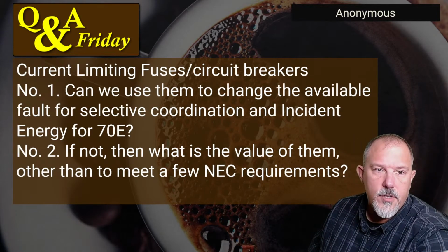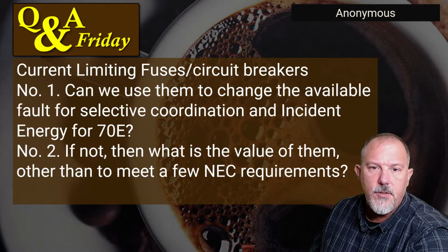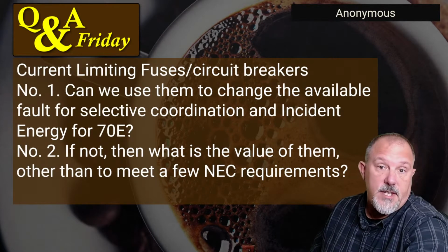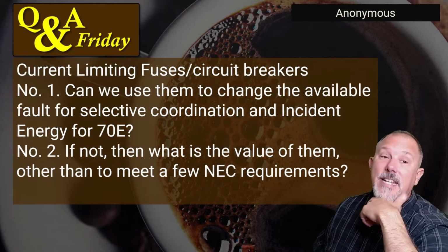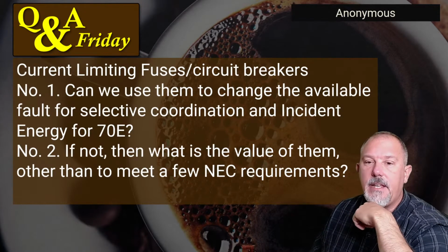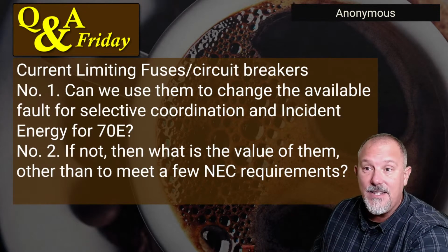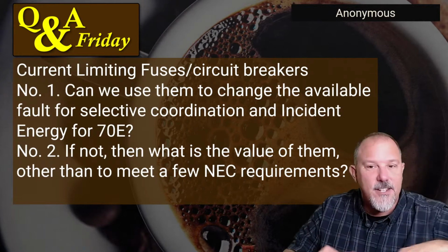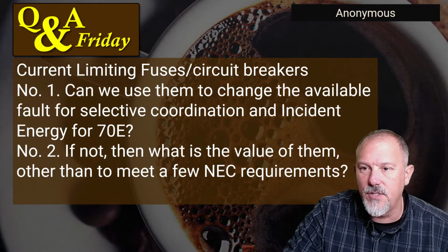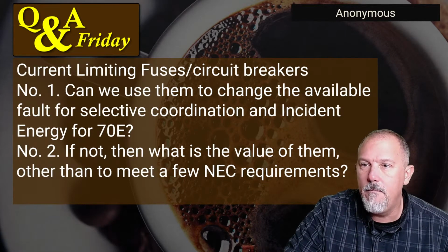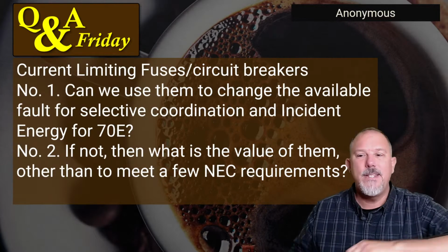Can we use current limiting fuses and circuit breakers to change the available fault? So it's the same topic, for selective coordination and incident energy for 70E. Ooh, and this aligns with Ryan Jackson. Ryan, if you're still out there, buddy, remember I mentioned 110.16(B).